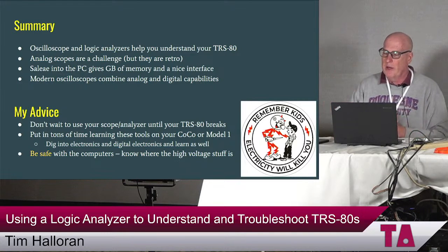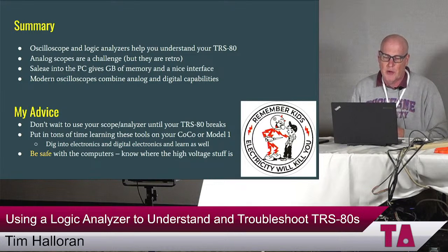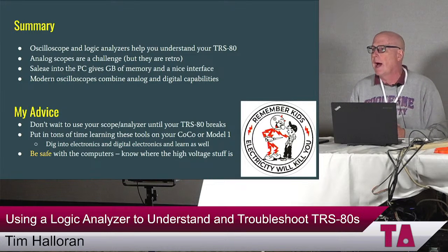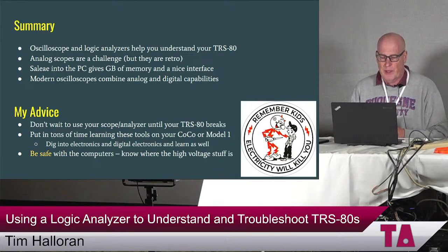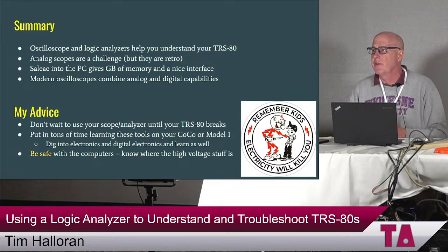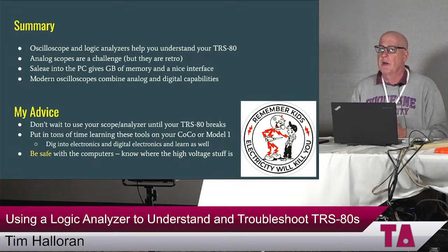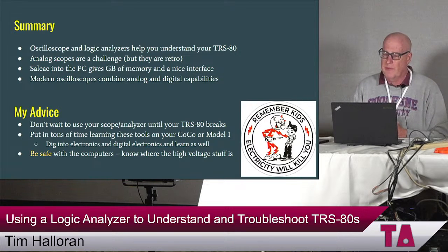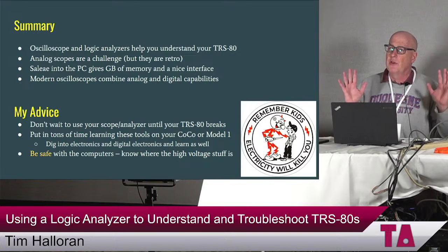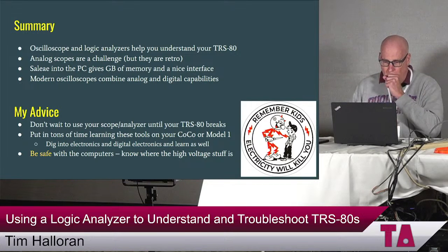Remember, kids, electricity will kill you. Be safe with the computers, know where the high voltage stuff is, and be careful. Wear gloves or things like that. I'll also add a caution on the oscilloscope. Most oscilloscopes are wall ground or earth ground, so you don't want to be poking around super high voltage stuff without knowing what you're doing. If you're poking around a TTL chip, that's probably okay.